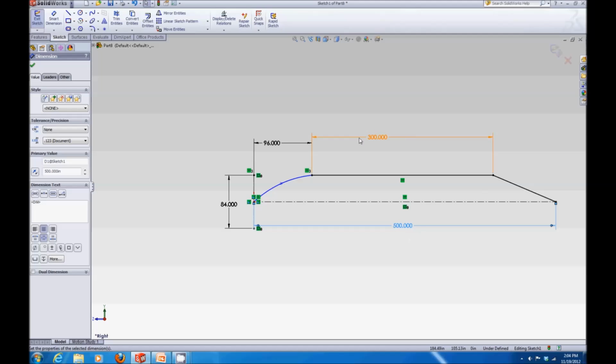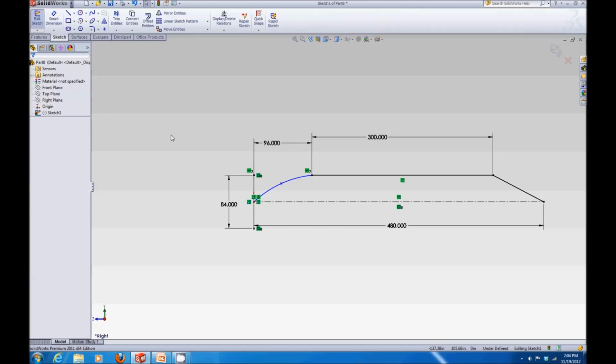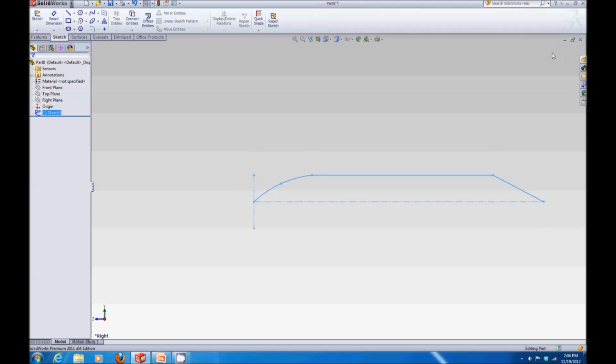But obviously we've already constrained our passenger section and our cockpit, so the only section that would change is our trailing edge, which might be beneficial when you're creating your aircraft, since the CG is going to change, and your trailing edge position of your horizontal and vertical might change depending on the stability calculations later on in the project. Okay, so we can go ahead and make that.